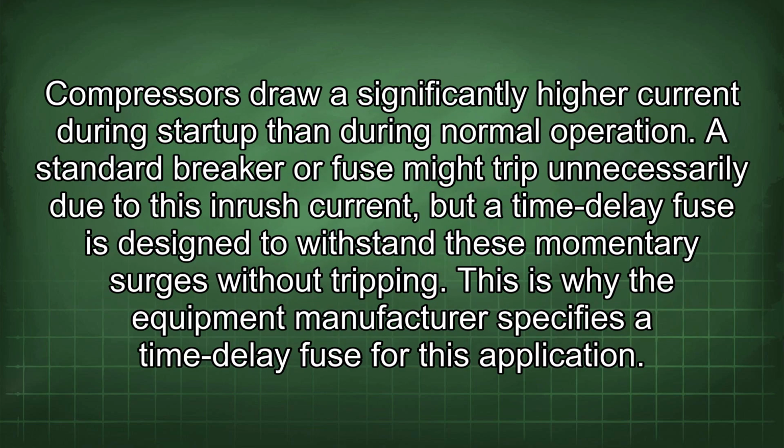Compressors draw a significantly higher current during startup than during normal operation. A standard breaker or fuse might trip unnecessarily due to this inrush current, but a time delay fuse is designed to withstand these momentary surges without tripping. This is why the equipment manufacturer specifies a time delay fuse for this application.